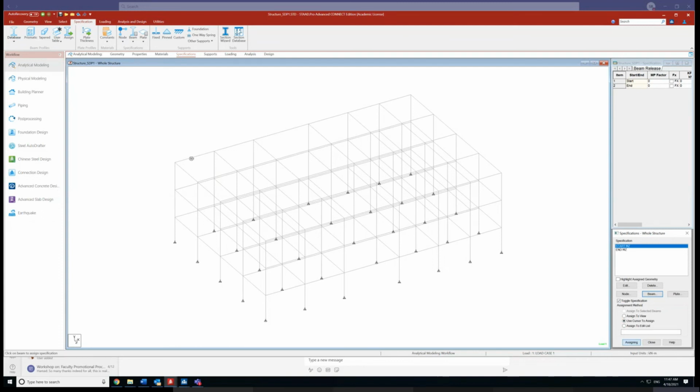So if I press there, then an internal hinge will start at this location. I can do the same for all these beams that are coming in this direction. I am releasing the top just to save time, and I can release these ends there like this. Okay, ends, this one here, this one at this location.